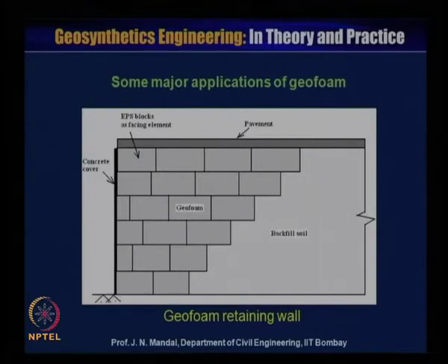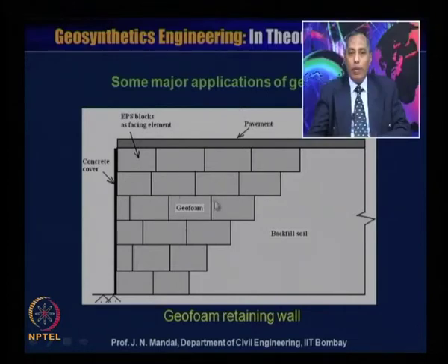This is a concrete cover and this is the EPS block, or expanded polystyrene block, or the geofoam material, and this is the pavement and this is the backfill soil. So here the geofoam material also acts as a retaining wall. So you don't need to construct a reinforced concrete retaining wall.